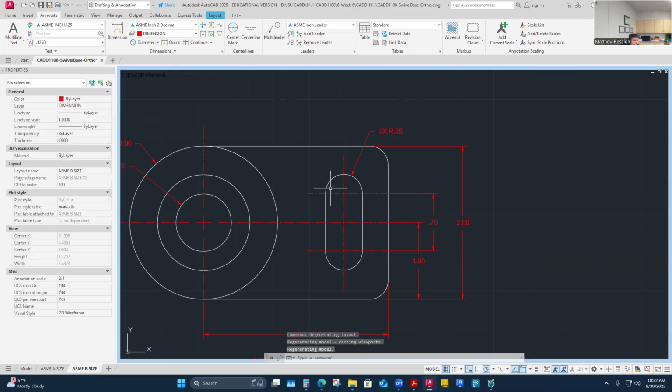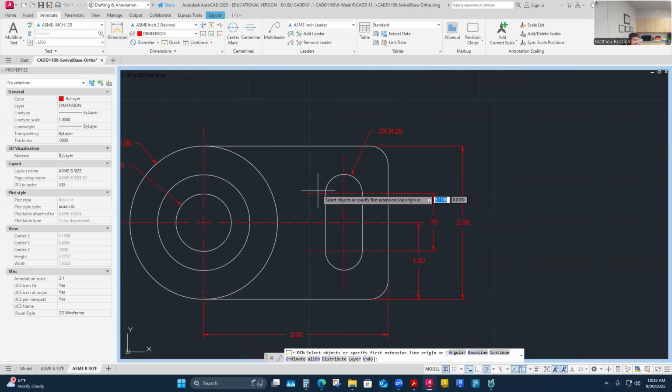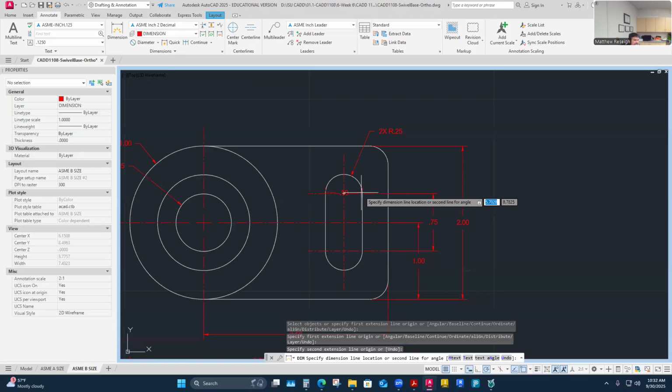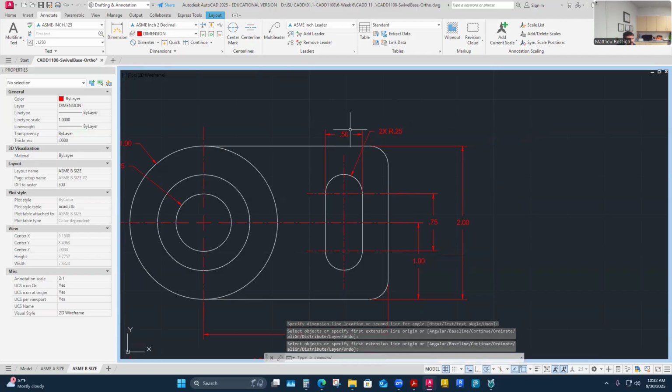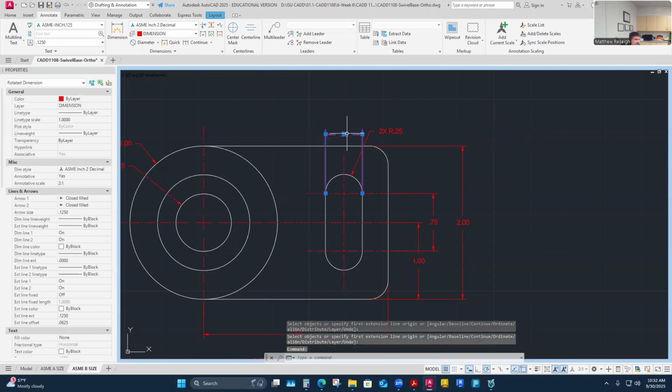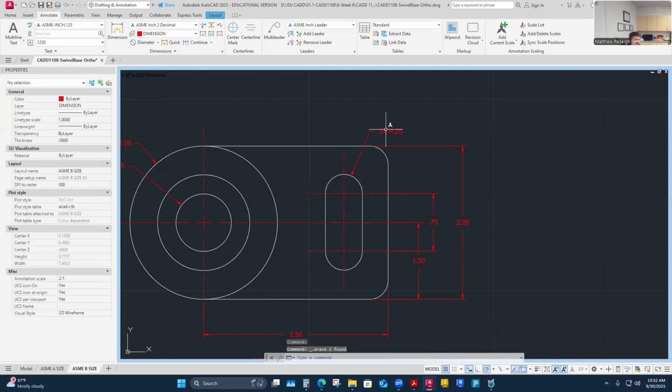Yeah, I wouldn't choose to put a diameter there because it's not a diameter, it's a radius. I could choose to put the linear width across though. It wouldn't be wrong to say, well, I sized it this way. And you would say, well, that's definitely sized. It's kind of saying the same thing as me. Is one better than the other? I don't know. I still don't have the radius callout if I do that, but my radius kind of covers both of those if I'm thinking about it.